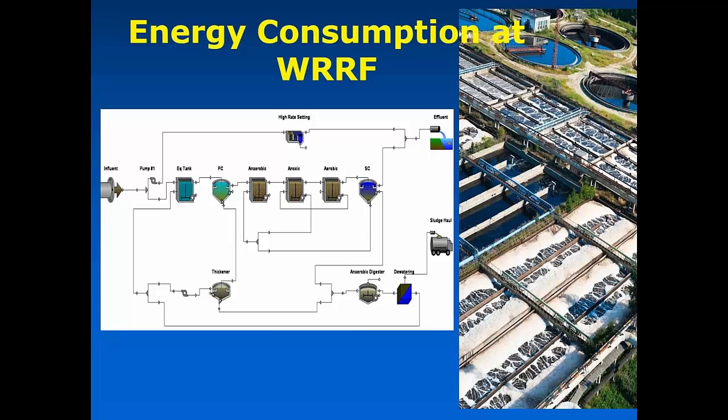So a large number of wastewater treatment systems require lift stations as the sewage is delivered into that plant, and you have to get it up to grade. Also RAS pumping, of course, and any other type of internal mixed liquor recycle pumping and so on. Those all require energy, and they all need to be assessed in a way to understand how that energy consumption is part of your system.